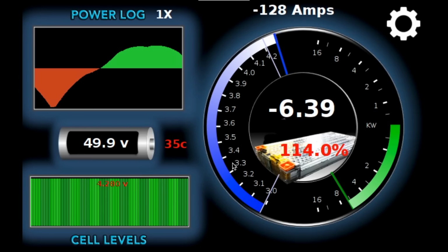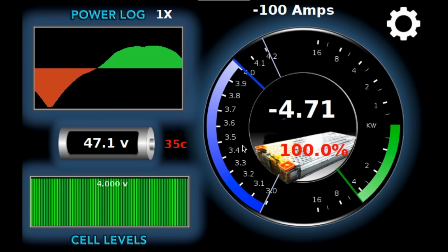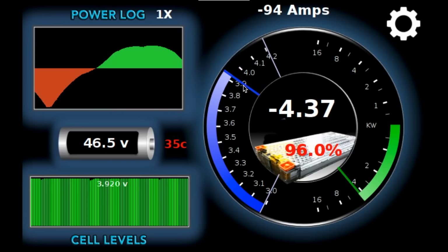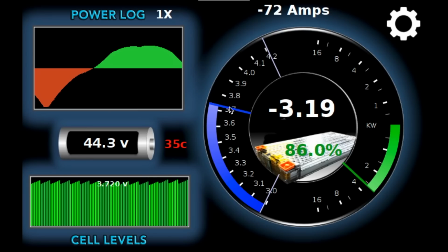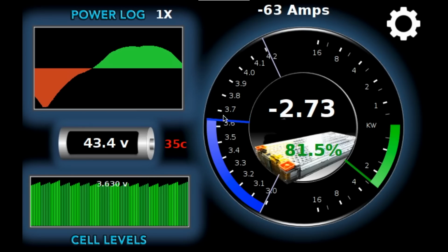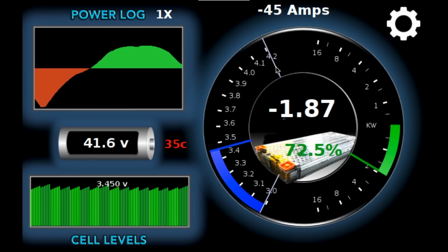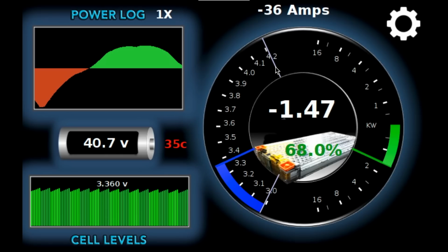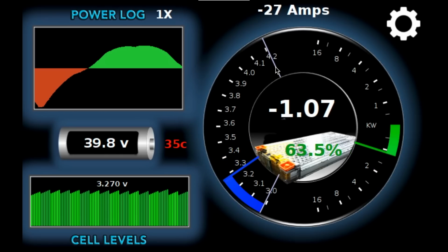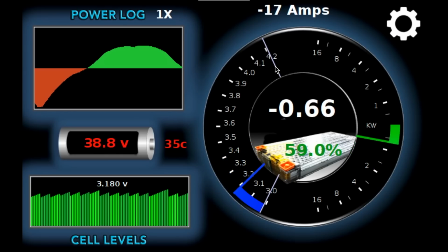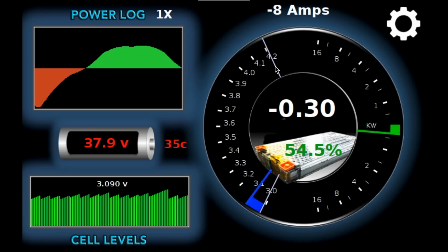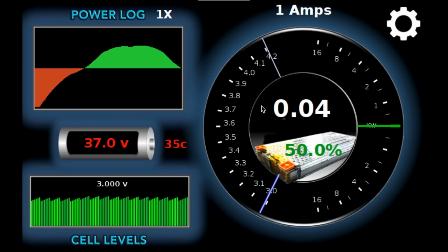Let's talk about voltage. And here we are displaying the voltage of the cells. And what we're actually displaying here is the average voltage of all the cells. And that ranges from 3 to 4.2. This line is what we set in our controller as our cutoff. This is where we would disable the positive contactor, well, actually both contactors.